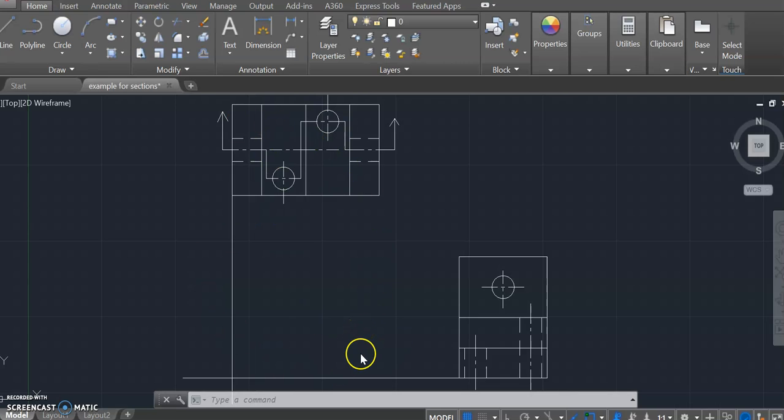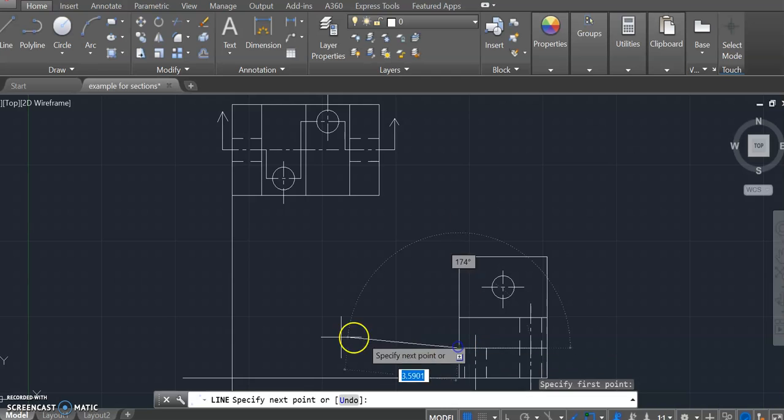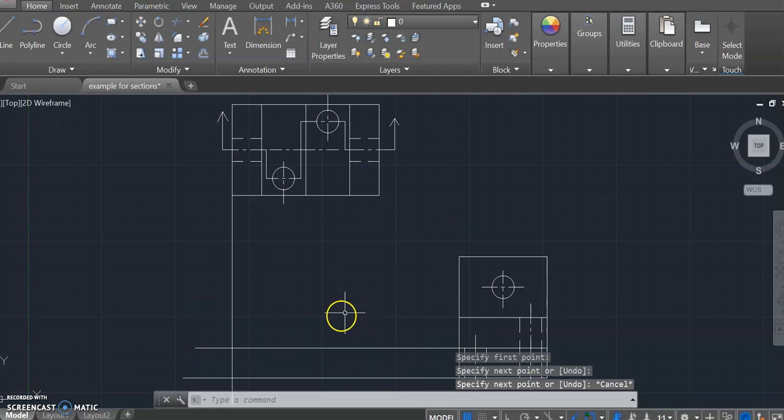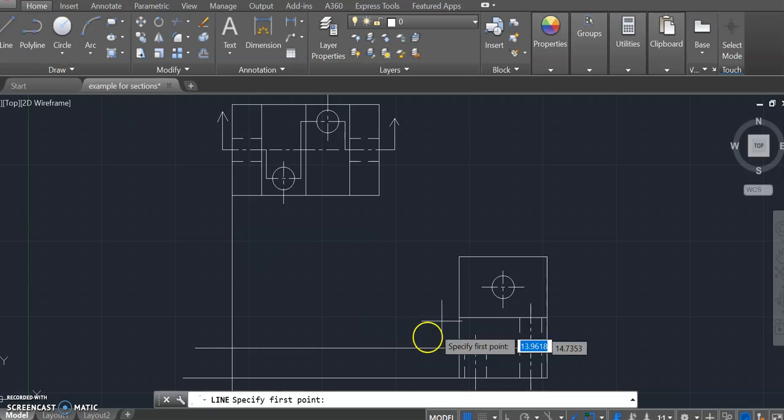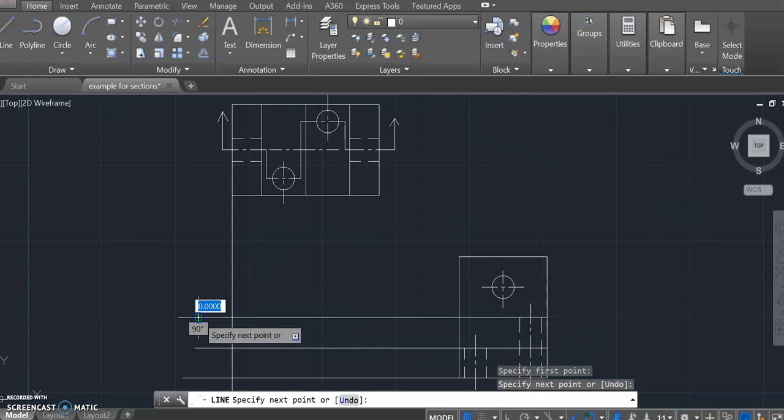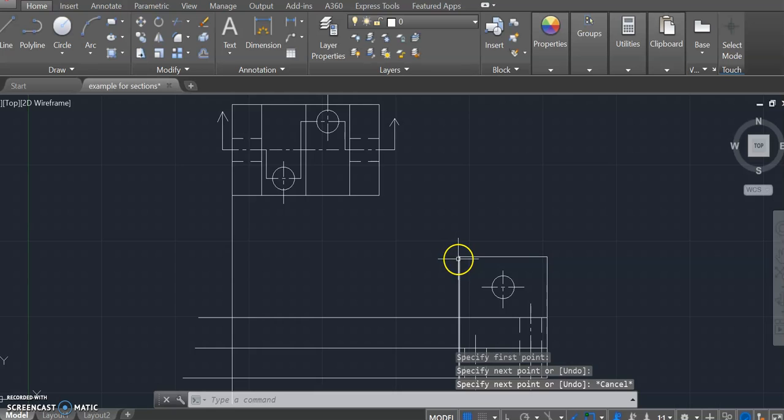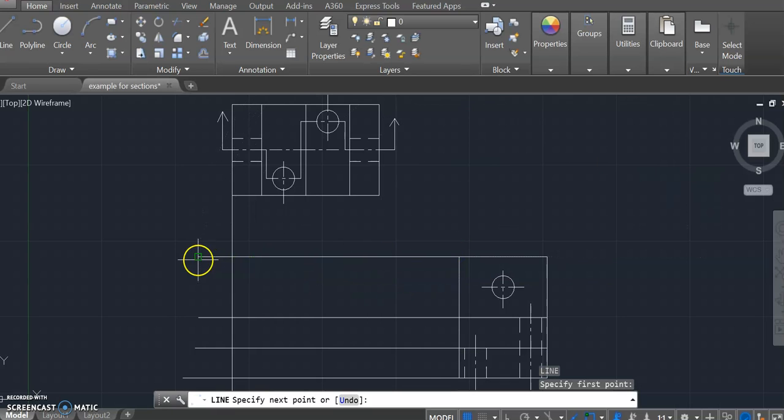So this is the top view. This is the side view of the object, and what this is going to allow me to do is going to allow me to get the dimensions that I need for my particular section view. So I'm going to begin by going ahead and projecting some lines over. That way I can get my appropriate geometry there. And I'm just projecting the surfaces over from the side view.